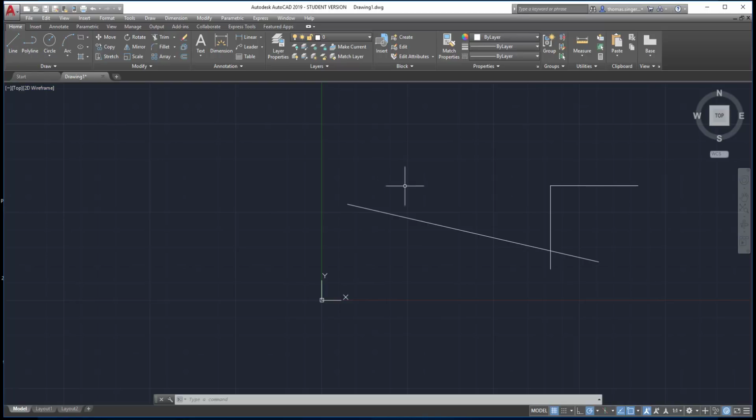I can tell if I start a line command, you'll notice that it tells me the length of the line, and it's also at 0, but you'll also notice that it locks in 5, 10, 15, 20, 25, 30. And that's all based on that polar tracking to lock in the angles. And the distance, I can get close, but to get it accurately, I actually need to type in the distance.